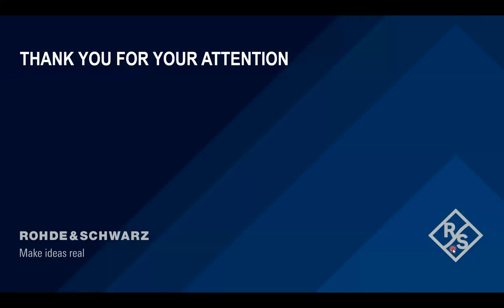Great, thank you. Next up, we had, how would you perform a measurement of drain source and gate source voltage of a high side MOSFET? And then goes on to say, I soldered directly on a MOSFET drain source and gate source pins, twisted cables, and then connected to my differential probe. And I'm seeing some weird effects on my gate source signal, maybe due to some parasitic effect.